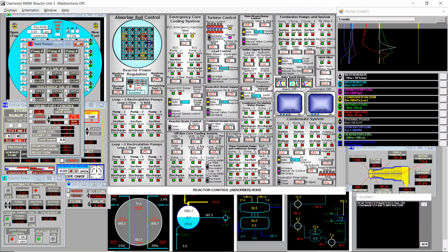Switch on the second pump. Open the discharge valve, and now we can switch to 3-element control and to main valve. Momentarily, probably the generated load will decrease because we're injecting some cool water into the system, I think. But you see here in the trend, generated load when we connected the 3-element control just went down a bit. So you always need to make sure you are around or above 50 or 70 megawatts before you connect the 3-element control.